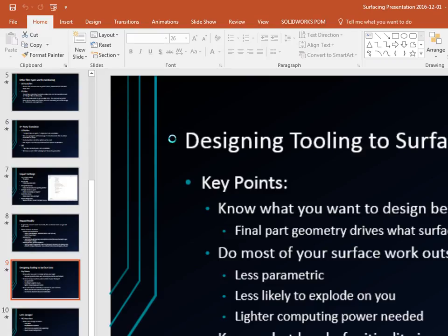Show me how you fillet surfaces. Like inside of a surface body. So you get a flat surface that you want to nest on, but then the sidewalls you've got offset with maybe two or three thousandths clearance, so you can get it out of your nest. I still want to fillet those corners that are offset. You can extend the surfaces out until it's a nice neat shape like a square, but I can't really successfully fillet it unless all my edges are nice and clean.